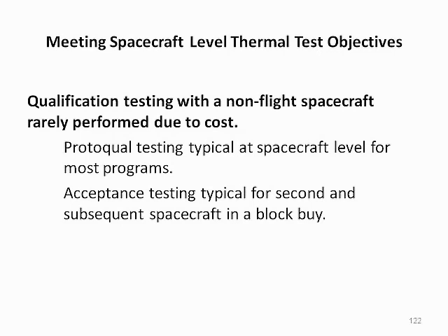While government test standards discuss spacecraft-level qualification testing using a non-flight spacecraft, it is rarely performed in practice due to the high cost of building a spacecraft that will never be flown. The most common practice for one-of-a-kind spacecraft, or the first spacecraft produced in a series of identical spacecraft, is the proto-qualification test. Acceptance testing is typically for the second and subsequent spacecraft in a block buy.